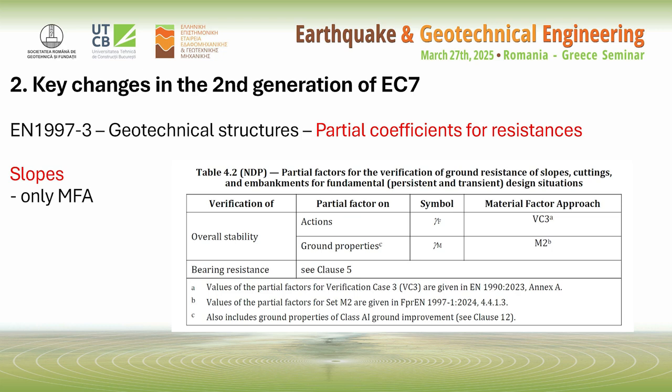I would like to draw your attention to the fact that all these tables with values that I am presenting are NDPs. That means nationally determined parameters. That means each country can change them if they have a good reason for doing it. We don't have to explain to anyone why and how we are doing it, but these are the default values and we can change them.